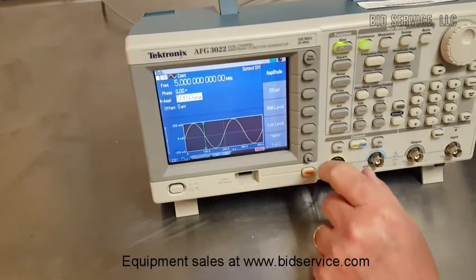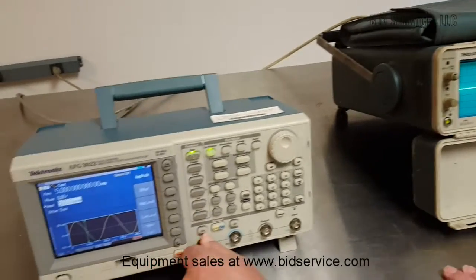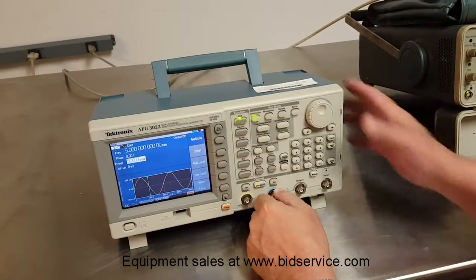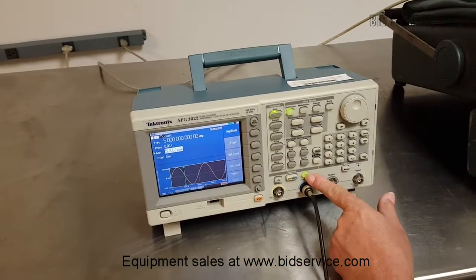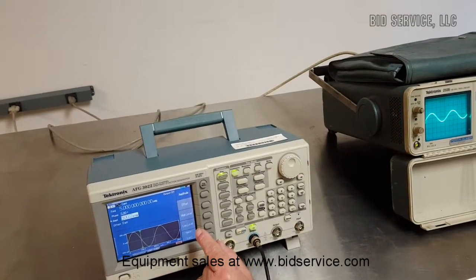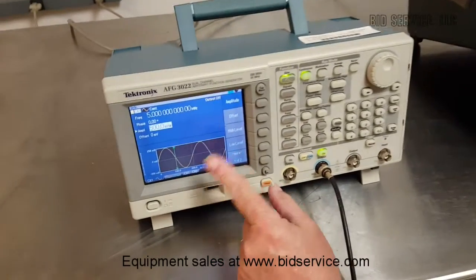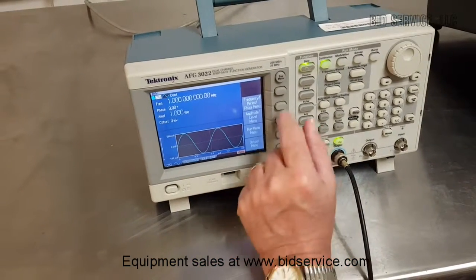I'm going to turn that channel off. You can see we now have a flat line over here. I'm going to swap my output to channel 2. Turn that output on, and as you can see, we've got exactly the same thing. So we're at 500 millivolts on channel 1. I've got to change this to channel 2, so we're at 1 volt.